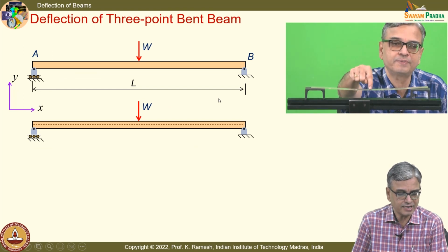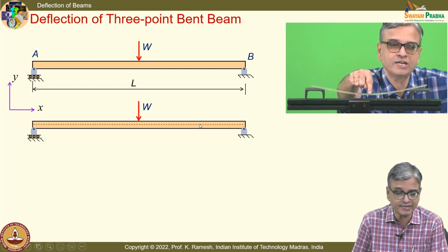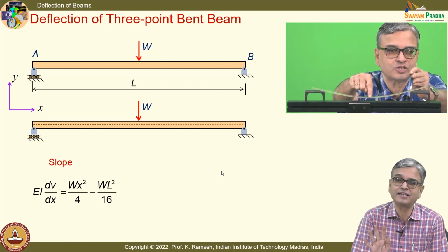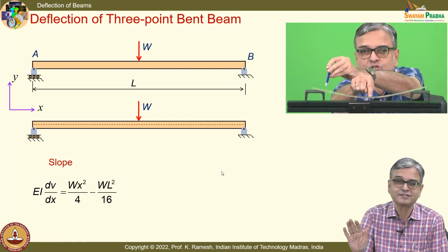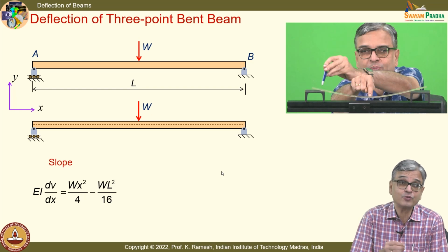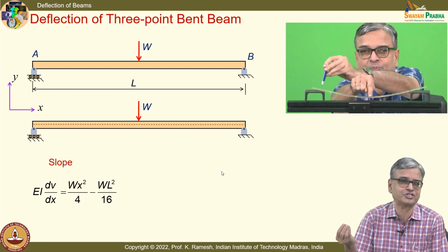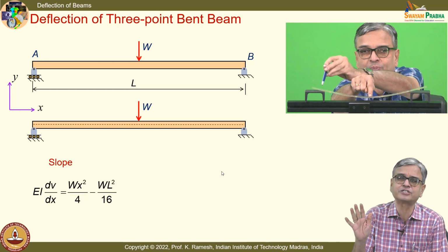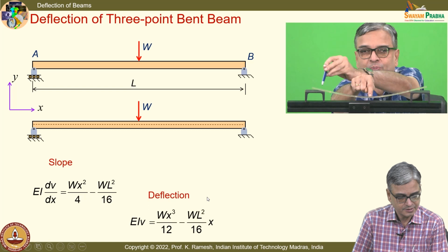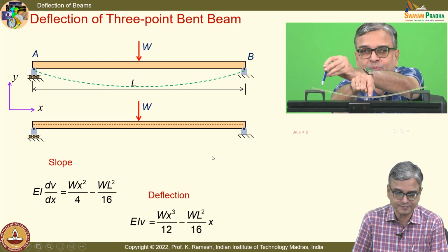So, I have this, and mind you, all these I am doing just for this line. I recognize the beam as just a line, I apply the mathematics only there, I ignore the thickness. We have found an explanation for that. Even though we investigated Poisson ratio plays havoc, that happens only when the deflections are very, very large. We never go near that situation. So, I have the expression for slope, I have the expression for deflection, and find out at important locations what happens.